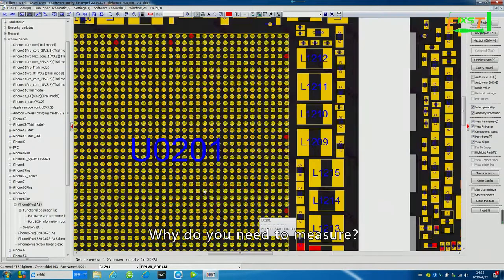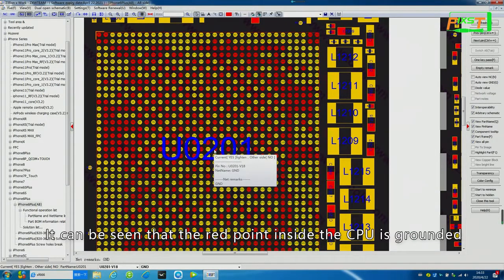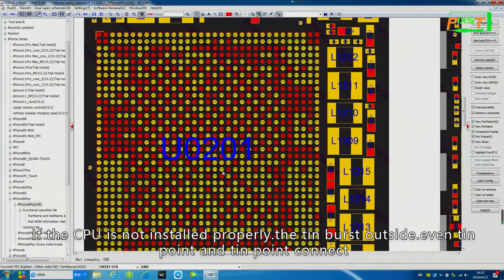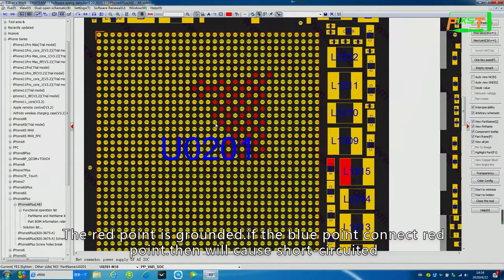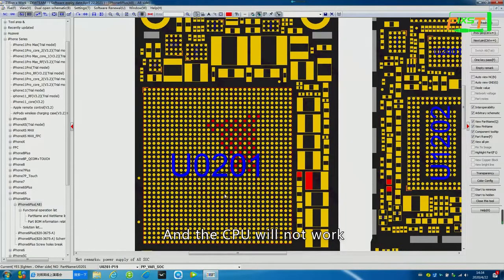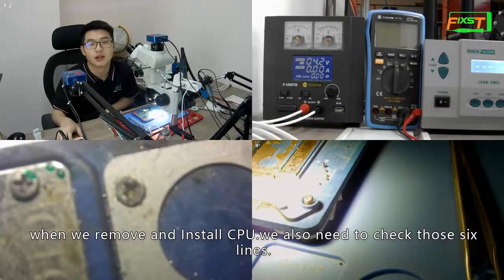Why do you need to measure? It can be seen that the red points inside the CPU are grounded. If the CPU is not installed properly, the tin bursts outside, and even a tin point and another tin point connect. The red point is ground. If the blue point connects to the red point, then we cause a short circuit, and the CPU will not work. When we remove and install the CPU, we also need to check those 6 lines.